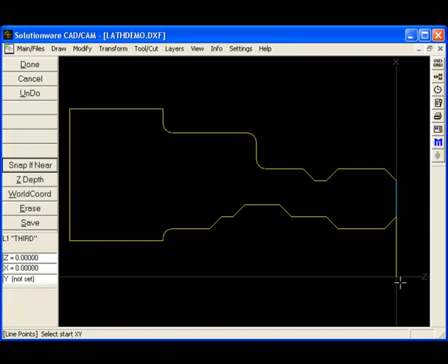Now for G-code, there's a way to stretch out the cut without artificially adding in these lines. But for Mazatrol, usually on a face rough, you're doing an edge process or a facing process. And unlike the bar process, instead of having a CPTX, CPTZ, it's just offsetting the shape lines. So for Mazatrol, we actually need to put in a set of lines going up the face here too.